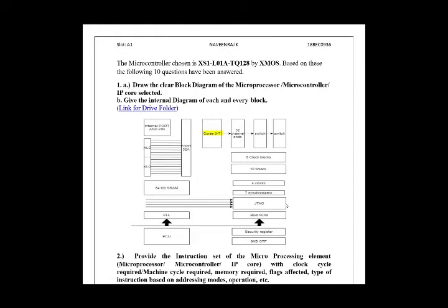This security register has many features: secure boot, disable JTAG, disable link access. There are a lot of security features, and this just specifies the access and how the boot program should get executed. The main focus is to execute the boot program securely, and for that we use these security registers, and this comes along with the OTP.